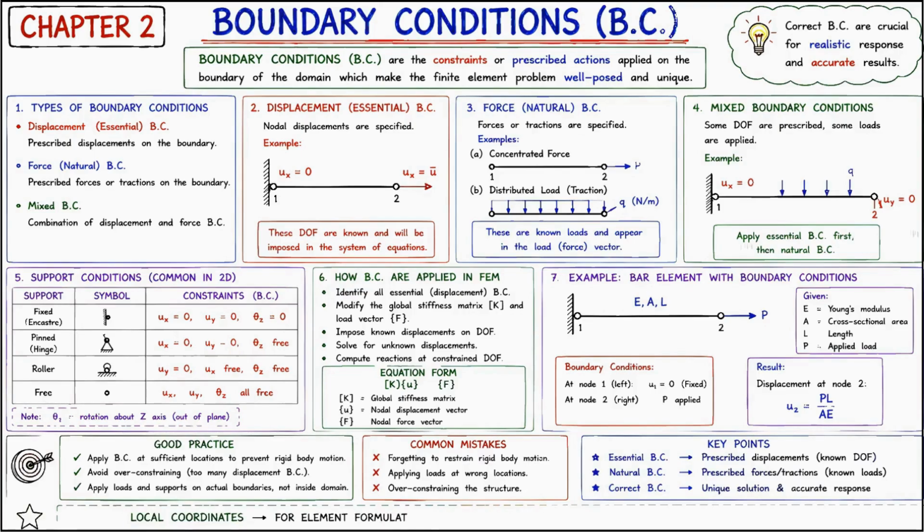So remember, essential boundary conditions specify known displacements. Natural boundary conditions specify applied forces. Together, they ensure a stable and accurate finite element solution.